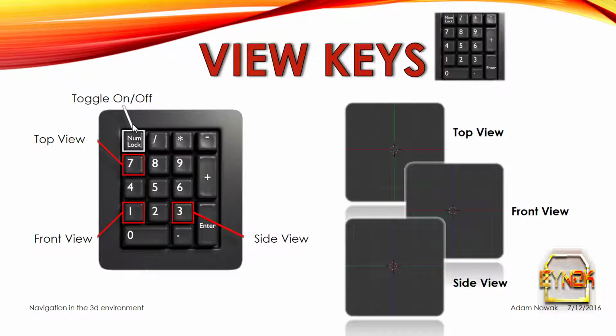We can also use a numpad to navigate the viewport. Pressing 7 will take us to the top view, 1 to the front view, and 3 to the side view, making sure that we have turned on the numpad by clicking numlock.